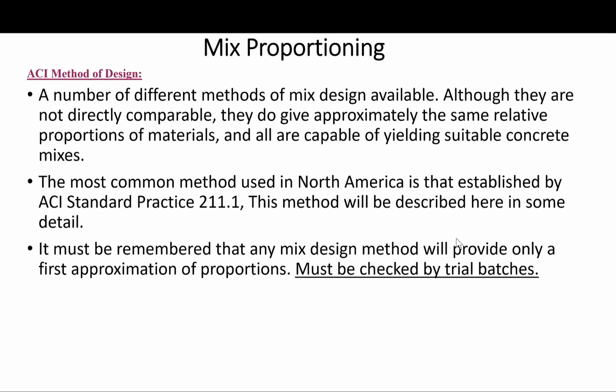So let's look at the mix design methods available. There are a number of different methods for mix design available. Although they are not directly comparable, they do give approximately the same relative proportions of the materials, and they are all capable of yielding basically suitable concrete mixes. The most common method used in North America is that established by ACI standard practice 211.1, and this is the method that will be described here in this class.